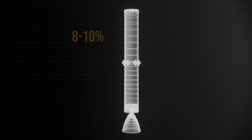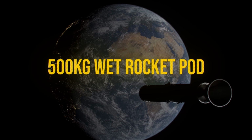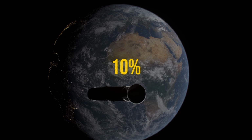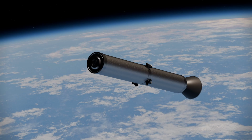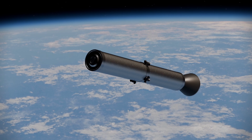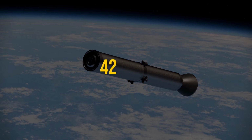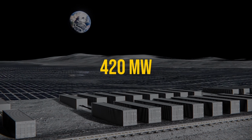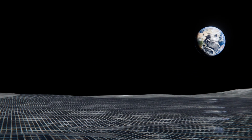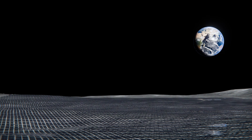But anyways, for this first order sizing, I think we can defensibly say that a 500 kilogram wet rocket pod is a reasonable baseline and would give us something like a 7% payload margin, with 10% being the structural overhead dry mass. So we're dividing that 17%, with 10% being the structure and 7% being left for whatever payload we're putting in it. Using the same acceleration and muzzle velocity as before, that would require about 423 megawatts of peak power, with an average power of about 212 megawatts during the 25.4 second launch, meaning the system spends about 12.7 seconds above 211 megawatts on its way to peak.